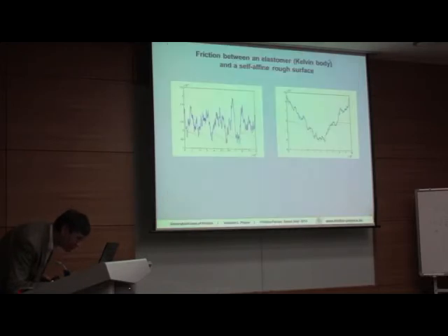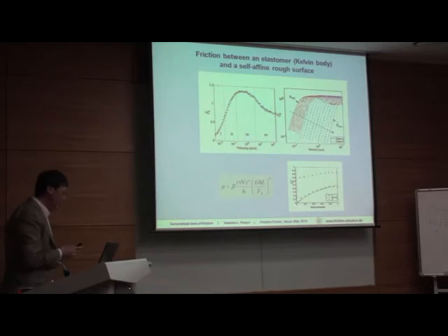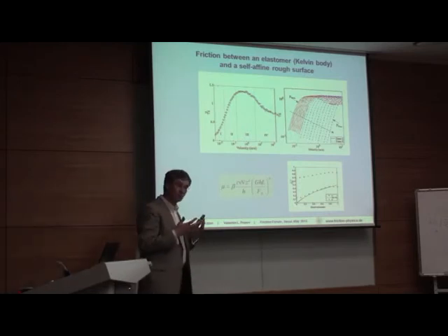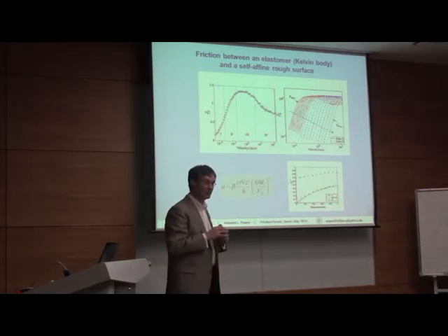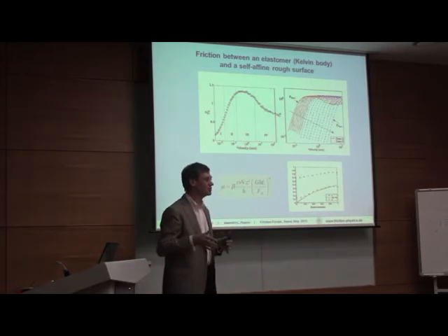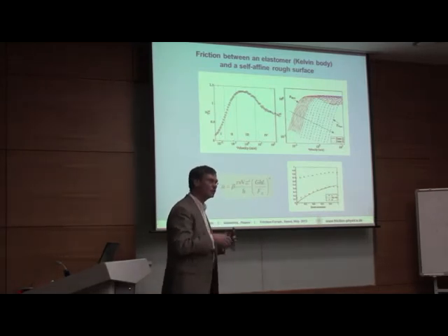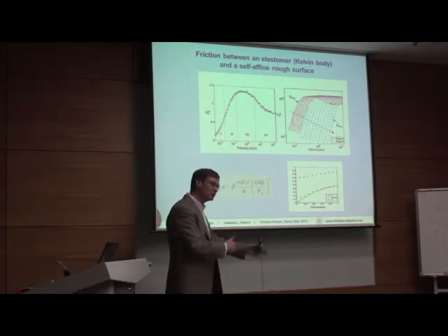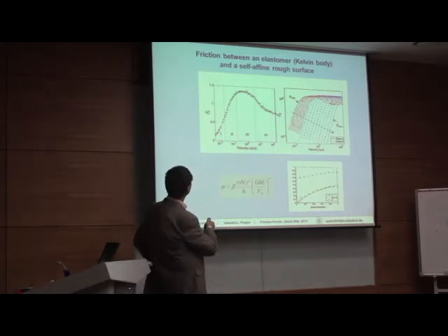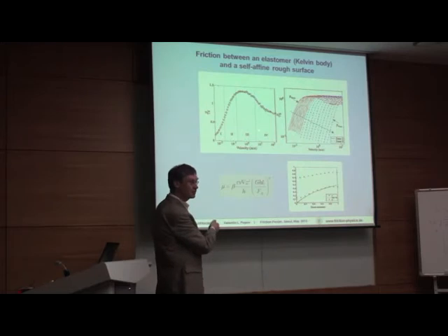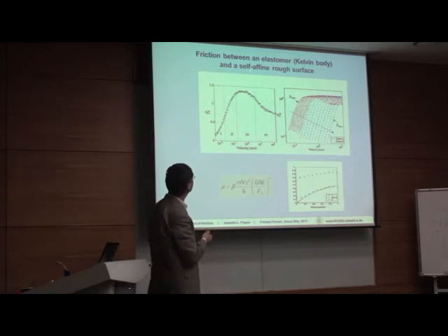And now, of course, because it calculates very rapidly, one can do parameter studies. What I will speak about is based on about 100,000 simulations for different values of shear modulus, viscosity, the smallest wavelengths, the Hurst exponent, and so on. And the typical form of the friction coefficient is a function of the logarithm of velocity. It is increasing, reaching a plateau, and then decreasing again.